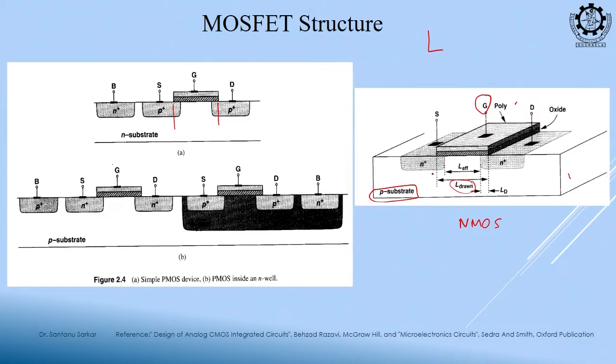It may diffuse a little bit. So, the actual L that we were trying to draw and what is physically the distance may differ a little bit, because of the implementation uncertainty, since at this micrometer length it is difficult.